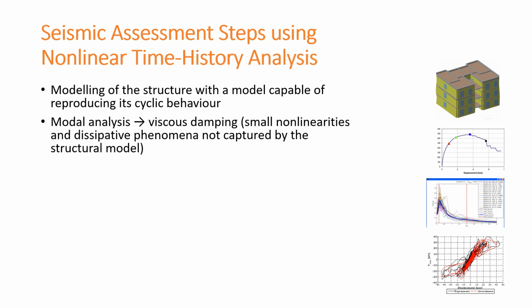Performing a modal analysis to set the parameters of viscous damping to account for the small nonlinearities and dissipative phenomena that are not fully captured by this structural model. This means that these damping values need to be very small, not 5%, but maybe 1 or 2%.